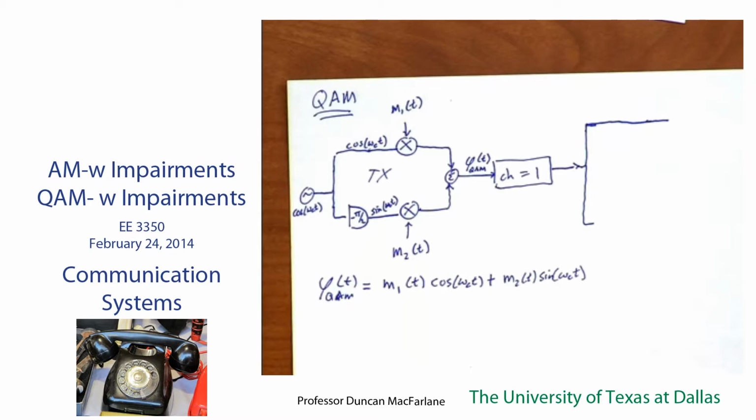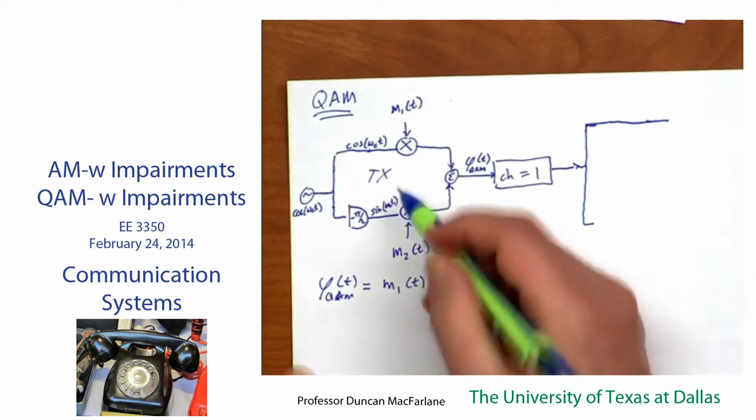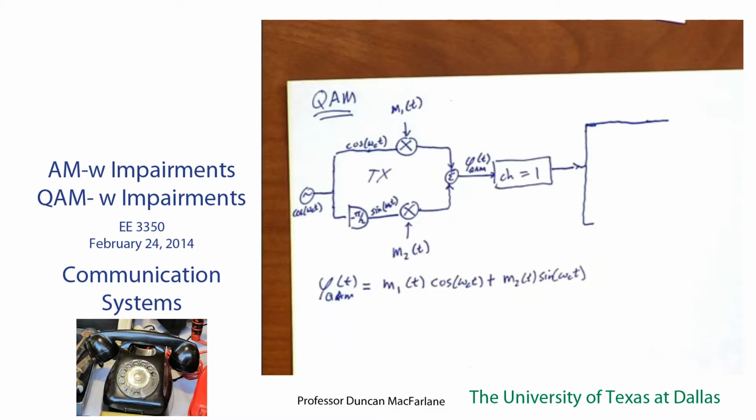So we've looked at two detectors for AM, right? We've looked at the coherent case, which uses a mixer and a local oscillator. And we've also used the diode as a rectifier, okay, to just pull out the envelope. And with a little bit of thought, you can recognize that the diode isn't going to work with this because I've got two frequencies, two sinusoids here. They're all just going to get rectified and muddled together. So the heterodyne system is what we really want.